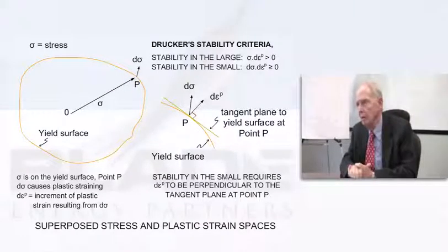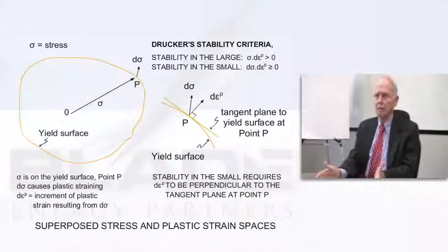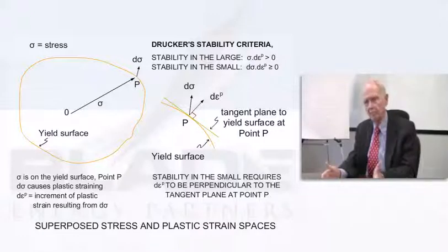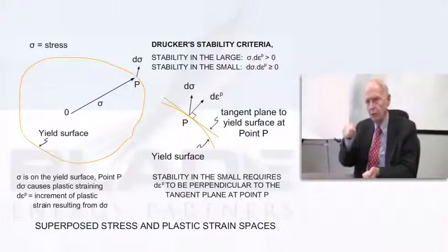Well, if you analyze the problem starting with a crooked beam, elastically, there's very little difference between the straight and the slightly crooked. But in plasticity, with the slightly crooked one, it starts to bow out, and the stress field is different from where you push it until it's fully yielded and then let it go sideways.